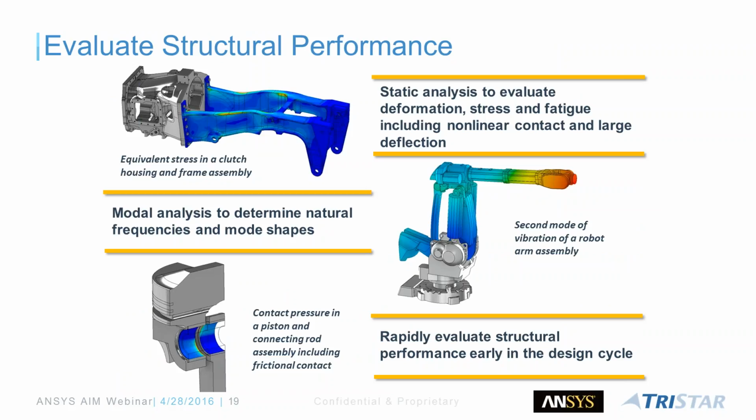Or sometimes you just want to do a pretty straightforward stress analysis on your assemblies or parts. It can detect contacts automatically. That's huge in assemblies, as you know, right? As you know, part level analysis is pretty straightforward. You bring in the part, apply a boundary condition, apply the load, and then run the analysis in most FEA tools. However, in large assemblies or medium complex assemblies where the interface between the components is quite important, it can detect contacts quickly. And then you can apply your boundary conditions and look at your stress and deflection result.